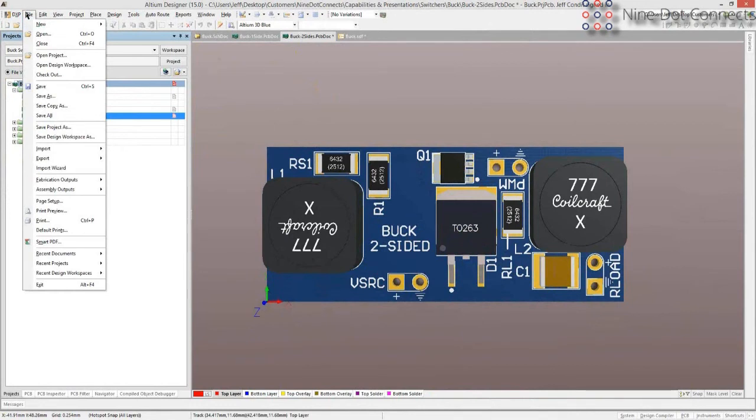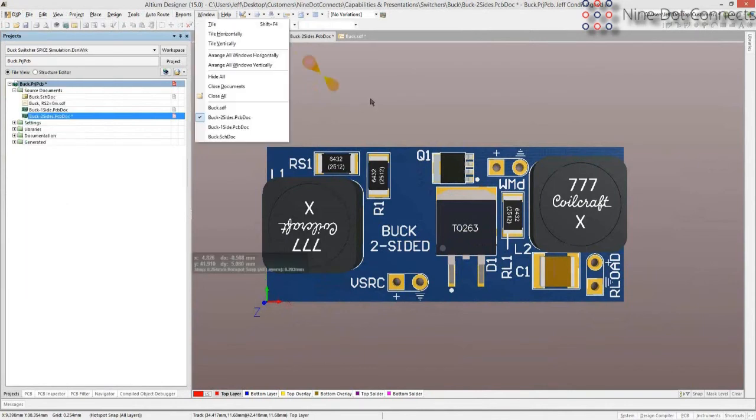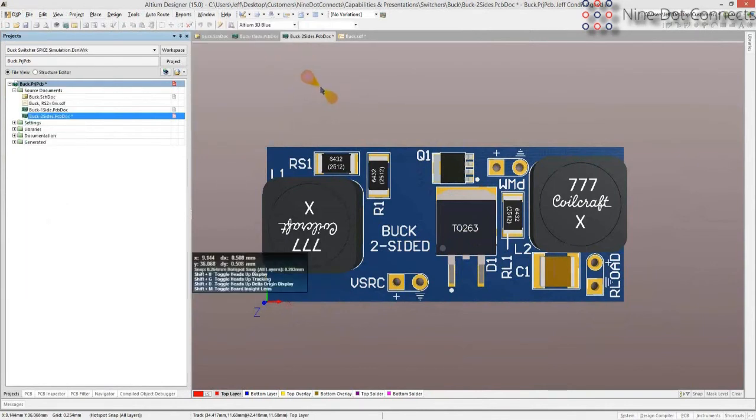Most people I know end up using Schottky diodes, and one of the reasons is because reverse recovery is much faster in a Schottky diode because it's a majority carrier device instead of a minority carrier device. Using regular silicon diodes is not as good. They take longer to turn off. So you don't have that same problem of trying to extinguish all the carriers. So most places it automatically does not become a problem. Also, as soon as you chase the carriers out, the current tends to stop. So again, majority carrier versus minority carrier.